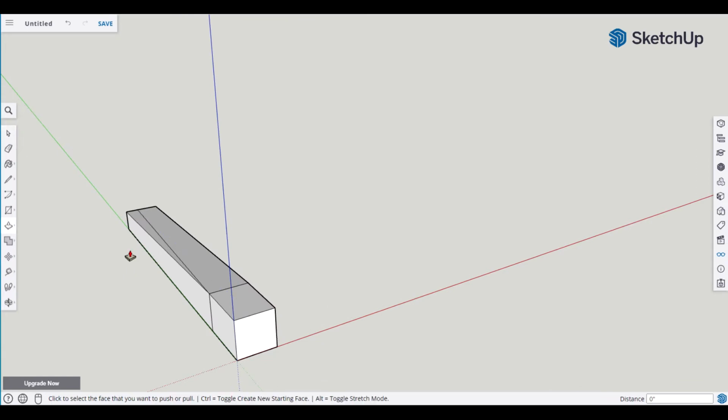Now let's select the push-pull tool, and we see here we can't push it that way. Space bar, push-pull tool on the top. We can't bring it down, but we can bring it up. Escape key, space bar. Instead, we're going to individually delete these sections. So we're just going to go ahead and highlight that, hit delete, and you can see it knocked away a good portion of it. Next, let's say we delete this. See, it takes away the whole bottom. We don't want to do that. Hit Control Z to undo what you just did.